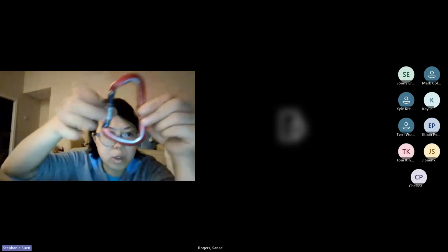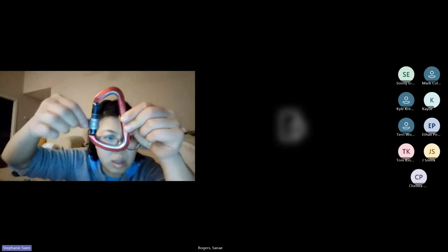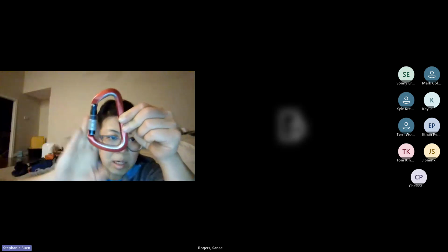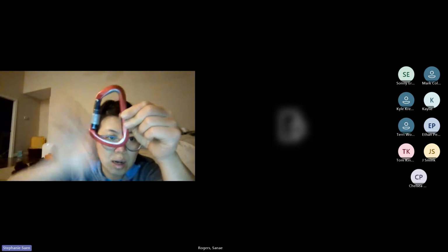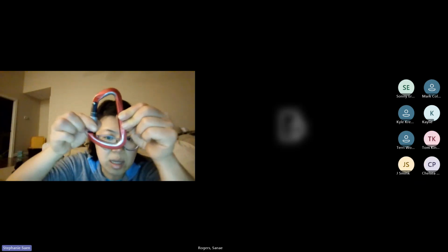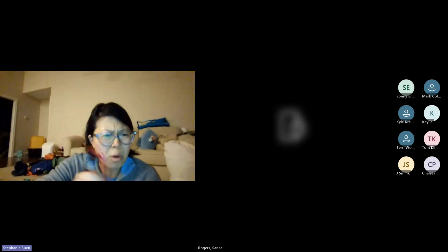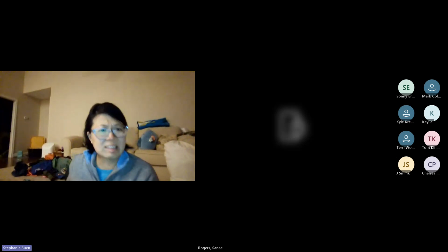So generally when you're rigging, you want this to screw downwards and be facing away from any obstructions, so that as you're climbing that rope and it's vibrating, it tries to stay in that closed position. Sort of all makes sense-ish.